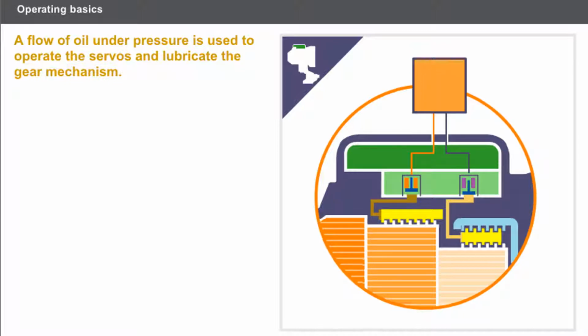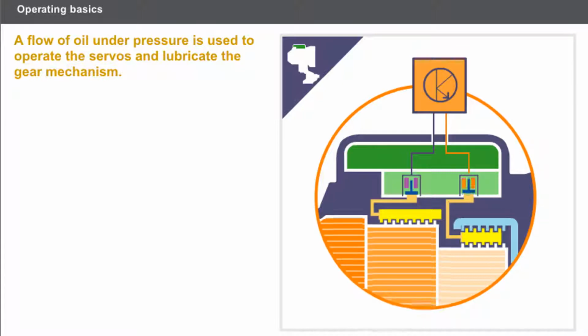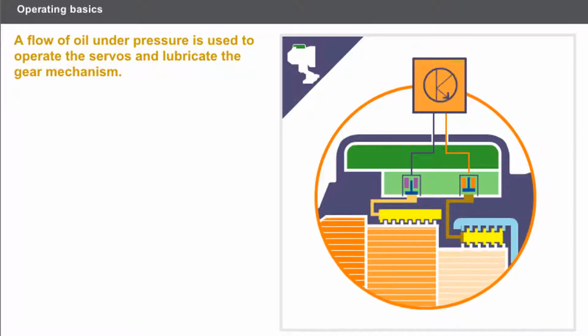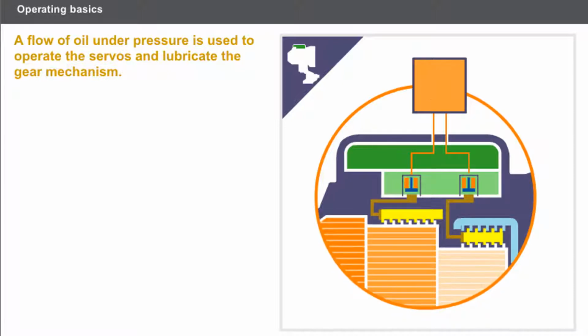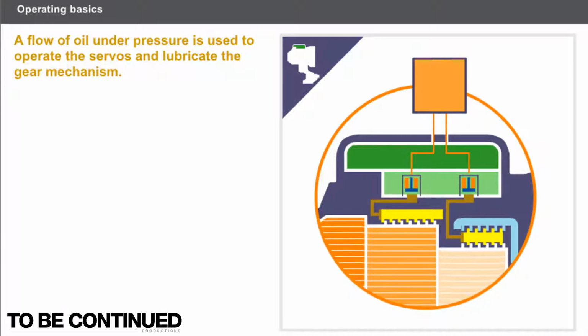Applying oil pressure to a brake prevents a gear wheel from rotating by connecting it to the gearbox casing. It then becomes a reaction component. Applying oil pressure to a clutch causes a gear wheel to rotate by connecting it to the turbine shaft. It then becomes a driving component. One or more servos may be activated depending on the ratio required.